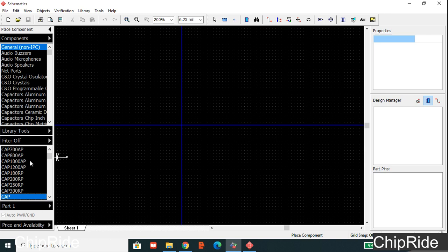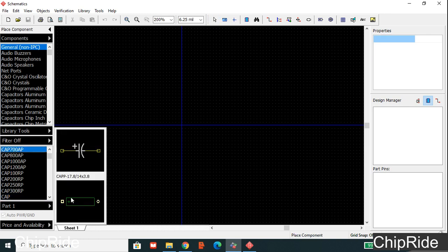Accordingly you can check the pattern for the particular PCB here. Here we can see this particular component, where this line is called the silk screen, and these are pads. This is a through hole component. Through hole components have leads which can get into the holes, so the leads are inserted and you can solder them. The basic discrete components are through hole components.